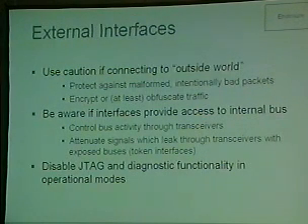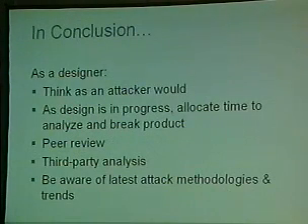One attack as far as token interfaces that we had looked at was with the USB keys again. We wanted to monitor which commands are being sent to the USB key and what data was being sent back and forth over the USB protocol. By doing that, we could possibly generate incorrectly formed USB packets and see how the device responds. So if we can monitor that traffic stream, which wasn't encrypted or anything because it was using the standard USB protocol, we could analyze that a little deeper.